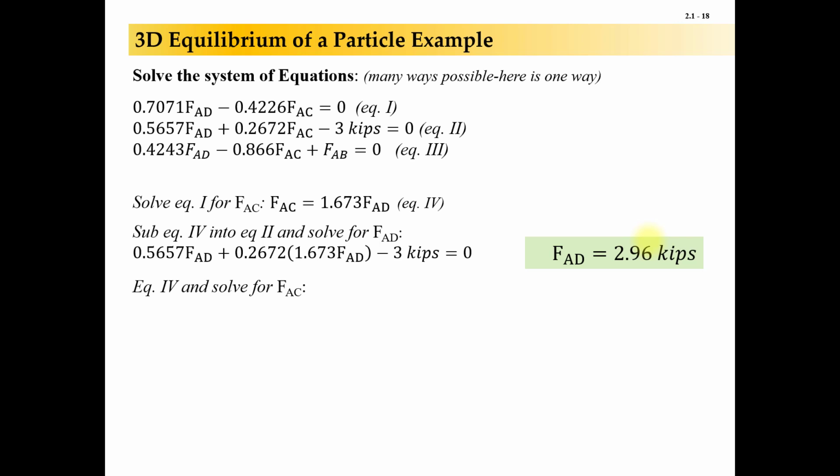That's interesting, right? 2.96 is almost 3. Remember that weight that's hanging is actually 3 kips. So do you think the rest of the cables are all going to just sum up to be equal to 0.04? No, you knew better, right? They won't all sum to the 3, because the 3 is the amount of force acting downward in the negative y.